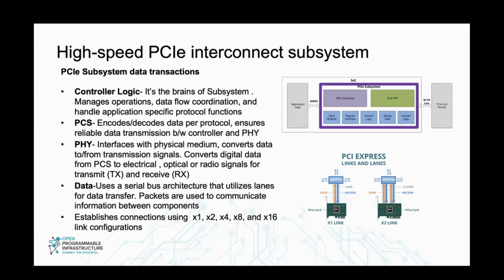Coming to the PHY, within the PHY we again have two sublayers. We call them PMD and PMA. PMD stands for physical medium dependent. It is a glue logic. Along with that, we have a PMA, which is a hard macro. PMA stands for physical medium attachment. So overall, the PHY would be PMD plus PMA.